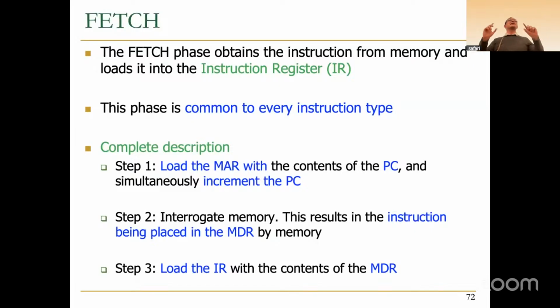What we have done, in other words, is we have interpreted the address, the program counter, as the address of an instruction, because we're accessing memory in the fetch stage. Now we're accessing memory using the program counter in the fetch stage, putting the data that's coming out of the memory into the instruction register.